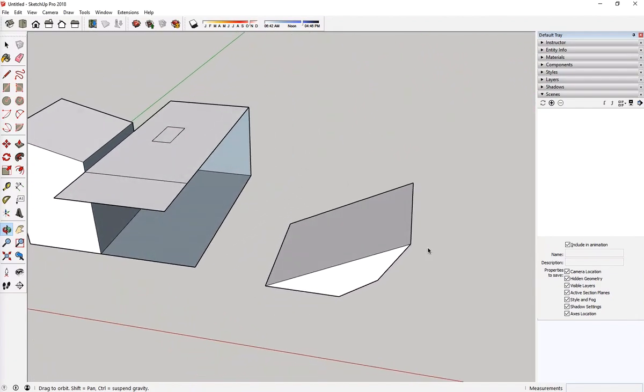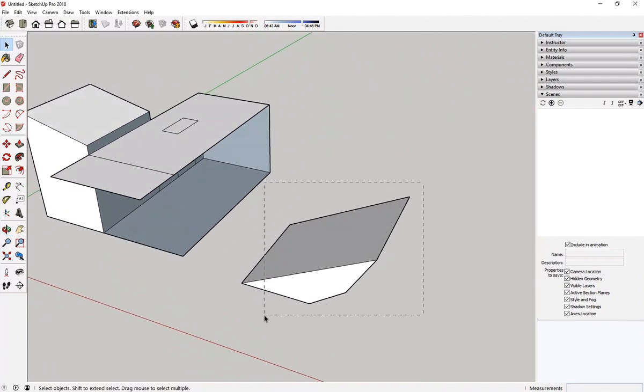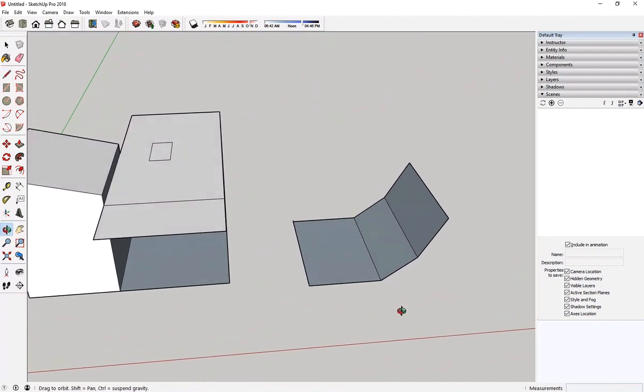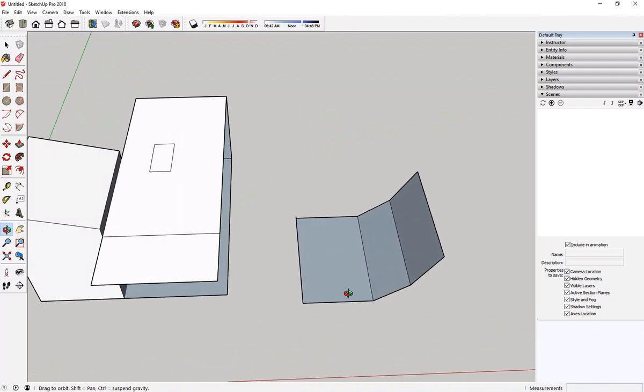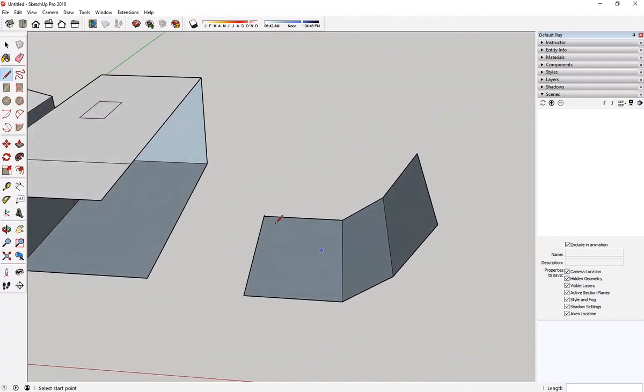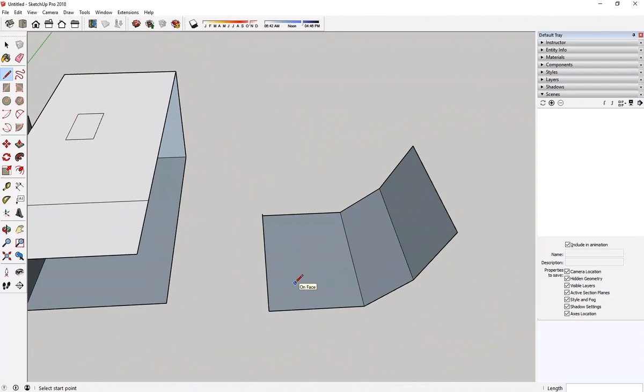So let's say, for example, let me just get rid of this surface here, and I'm just gonna add multiple lines this side and this side. So I have multiple surfaces on this drawing, and now I want to create a geometry out of this. So I want to create one box here, one box here, and one box here. Push and pull tool is going to be basically helping me to create that type of geometry.